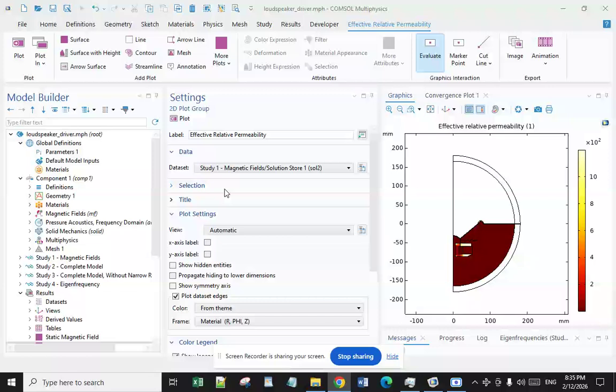The second advantage is that electromagnetic acoustic transducer is a non-contact method, although proximity is preferred. A physical contact between the transducer and the specimen under test is not required. The third one is dry inspection. Since no couplant is needed, the electromagnetic acoustic transducer inspection can be performed in a dry environment.